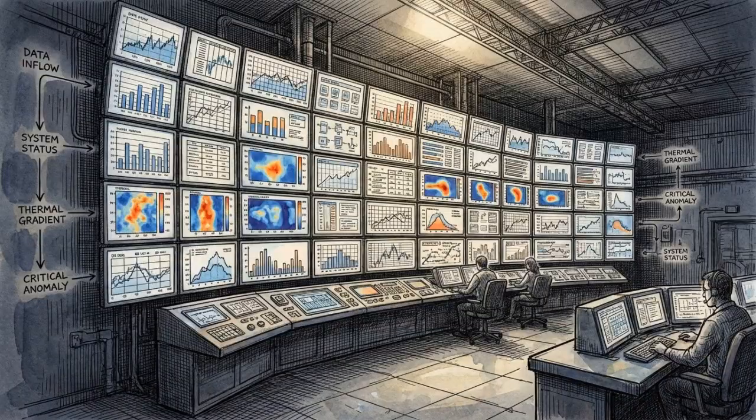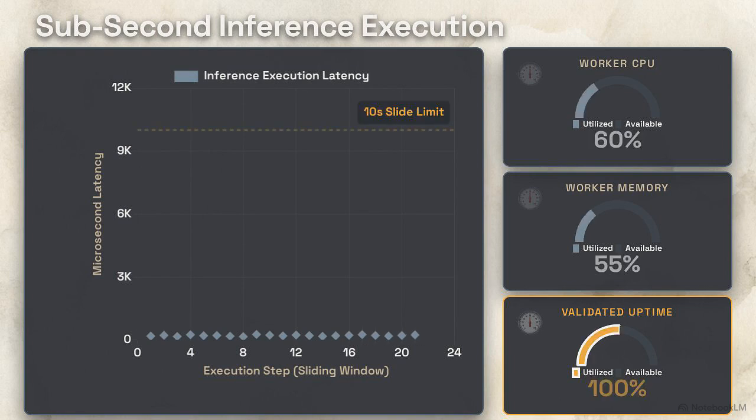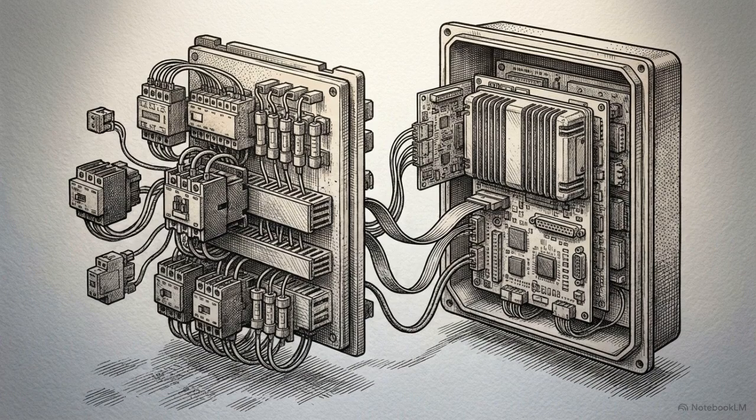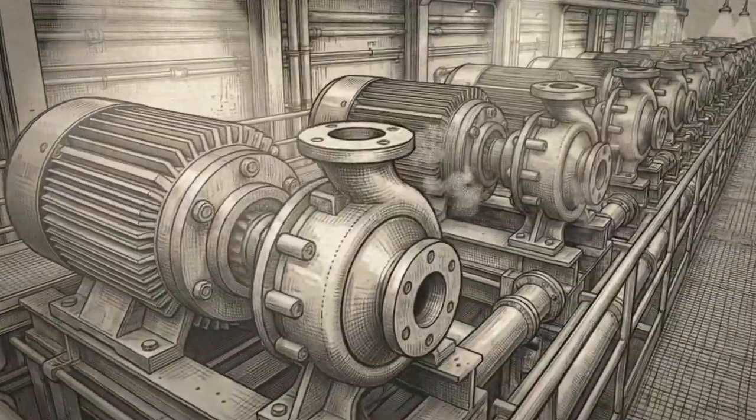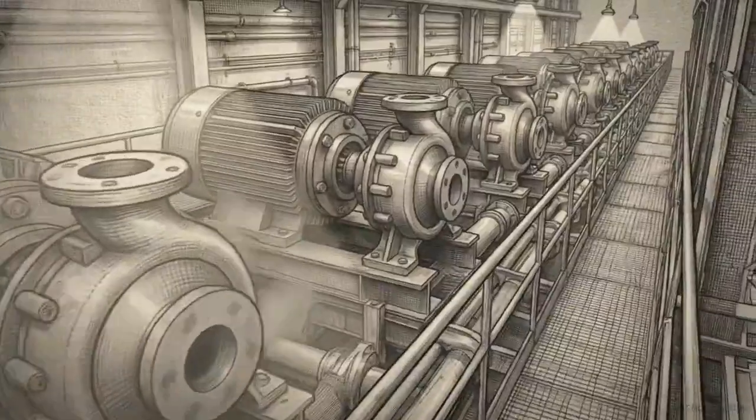The entire runtime is monitored by an observability stack. OpenTelemetry and Prometheus track the microsecond latency of the inference loop, while Grafana visualizes the analytical health of the worker itself. True industrial analytics requires stateful processing, strict functional boundaries, and deterministic electromechanical gates. When we bound our algorithms within the hard limits of physical reality, we produce intelligence the plant floor can actually trust.